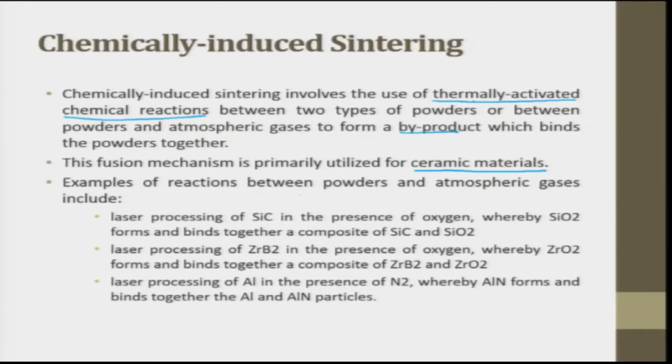Examples of reaction between powder and the atmospheric gas include laser processing of SiC in the presence of oxygen, where SiO2 is formed and binds together the composite of SiC and SiO2. You see, in the presence of oxygen, it is dissociated and forms SiO2.